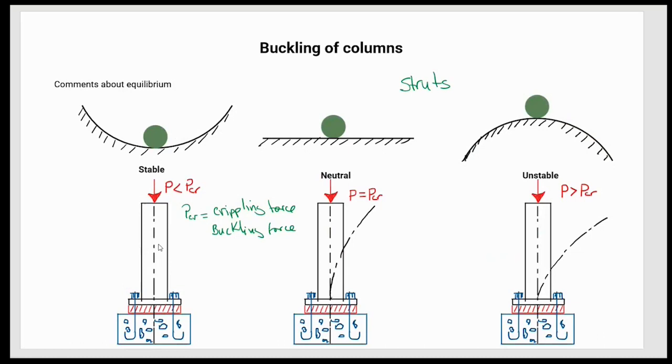And struts are, in a sense, columns, but they are just not oriented vertically. If you have a structure like this one that we have seen in many roofing structures, like a warehouse or something that you are designing, where you have a couple of columns holding it, and then you have these kinds of elements here, these elements here are called struts.